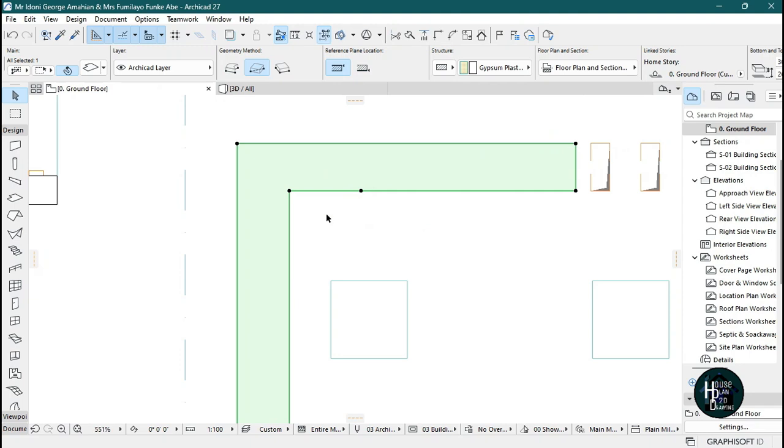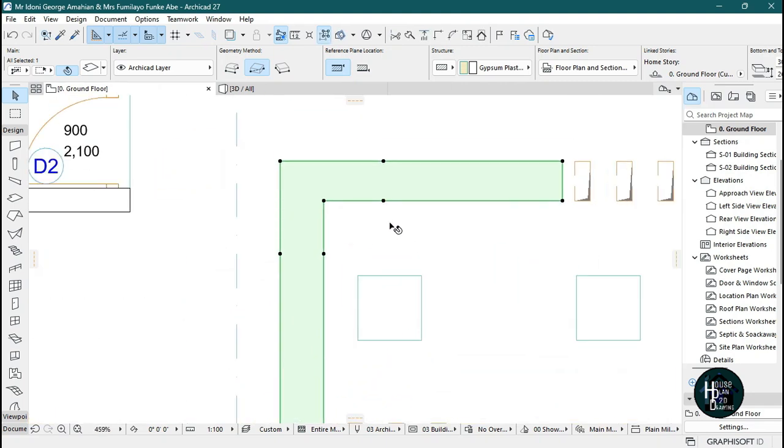So just click on this edge tool, and let's select insert new node. Click this and select insert new node. Click this and click this again. Okay, so once you've done that, I want you to come and select this split tool. Once you selected the split tool, click this node, drag it down like this, click, and select this side. Okay, now we've cut out this side from this side.